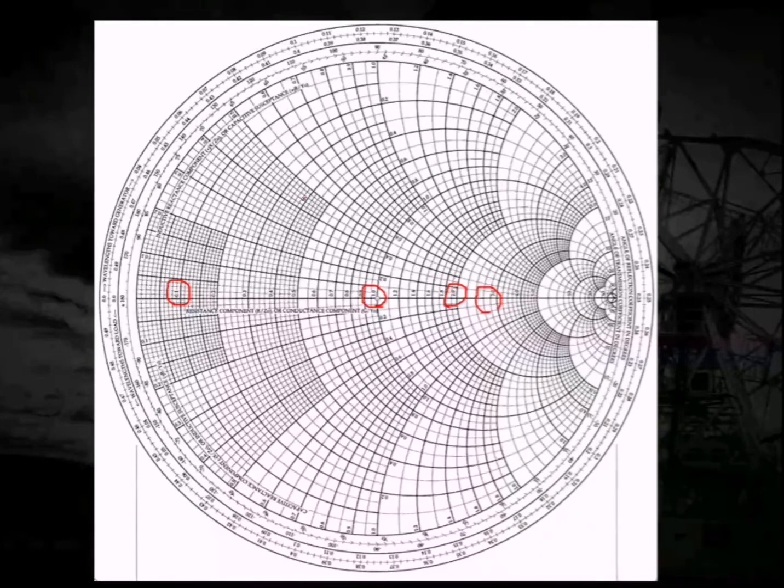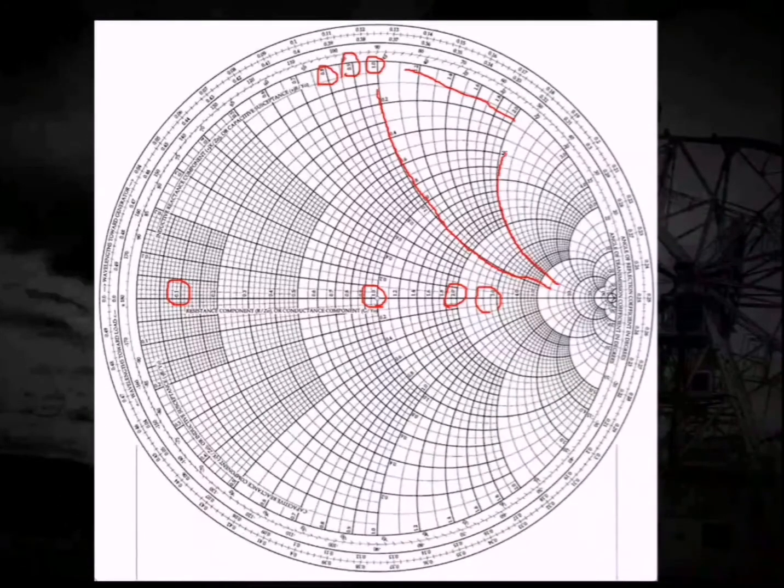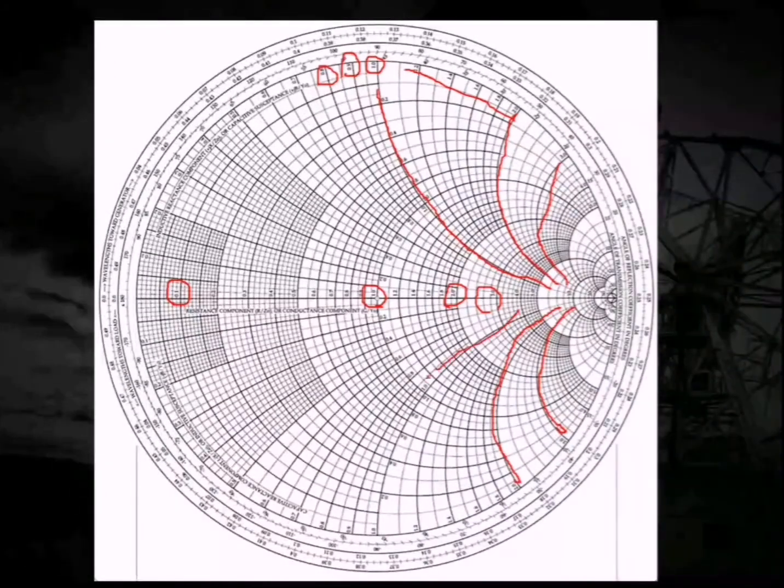Similarly, for the imaginary circles also, you can find the values over here. This is value 1, this is decreasing 0.9, this is 0.8, and over here it is increasing. So if I look at the reactance circles, these are like this. This one is for the value 2, this is for the value 1, then next is for the value 3. These are for the positive values of XL, and when I move to the negative values of XL, I will get these. This is for -3, this is for -2, this is for -1.